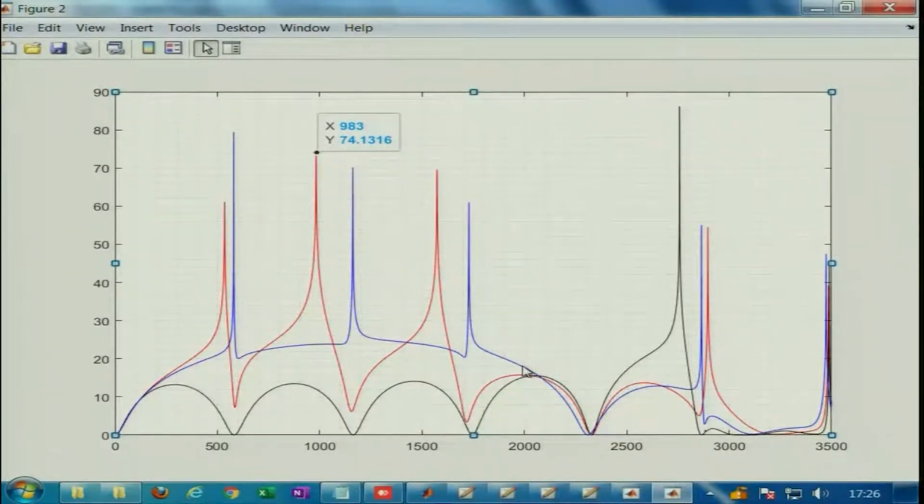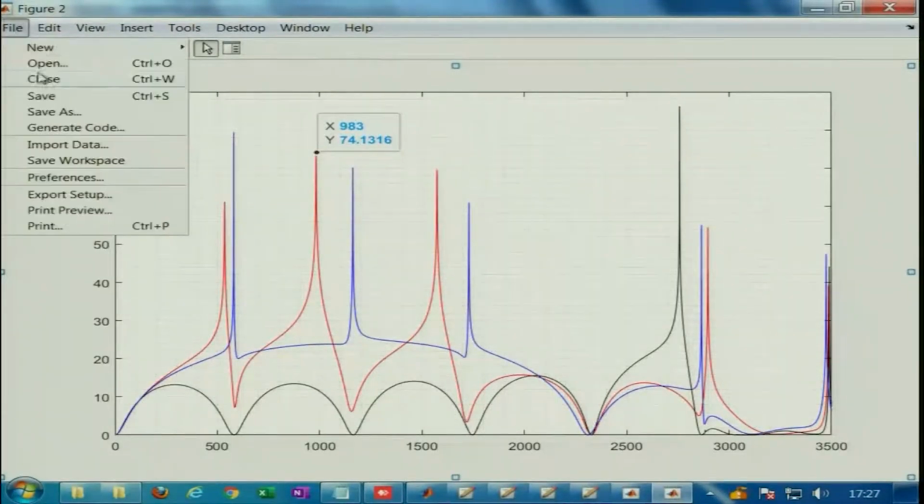We can still do better by attaching a Helmholtz resonator as a side branch to the extended inlet and outlet muffler, but that is a separate discussion. Now, basically compare the performance with the simple expansion chamber and also with the non-tuned one. This peak is really cancelling out the trough, and so is the second peak cancelling out this trough. It is doing really good, and just by tuning we can get wonderful results. So, I will save this file also.